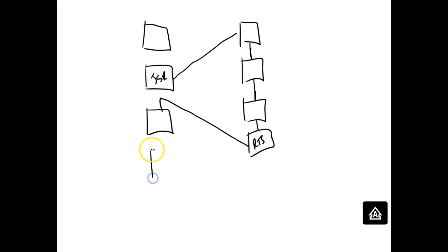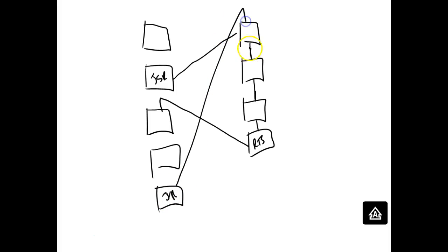But down here later on, I might want to JSR to the same subroutine. Then it would come up here and run through the subroutine again, but this time it's going to go back to the next rung after that JSR. It'll always come back to the rung under the jump subroutine. So you can use the same subroutine over and over again, and that's what's neat about it. In the old days of programming, before they came up with this, you had to literally repeat the rung.